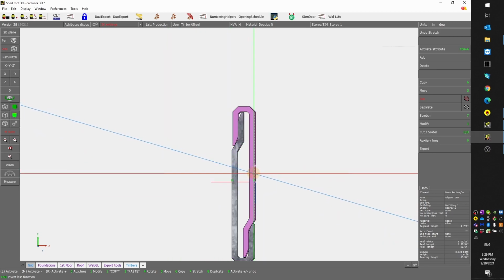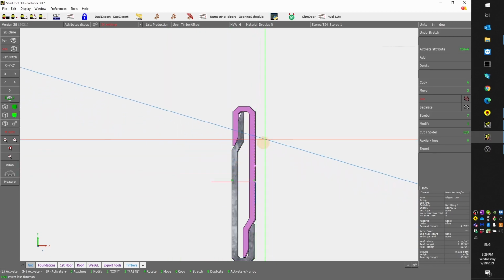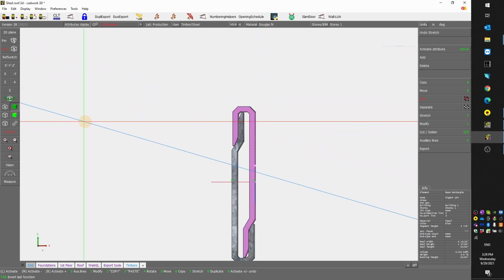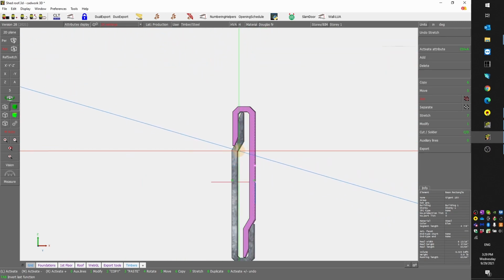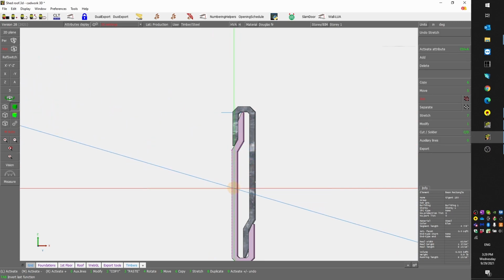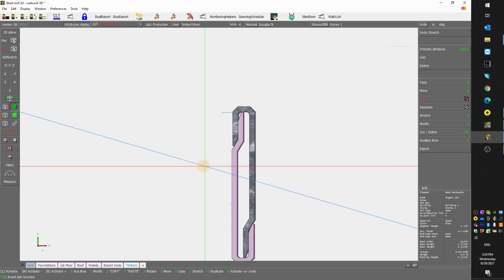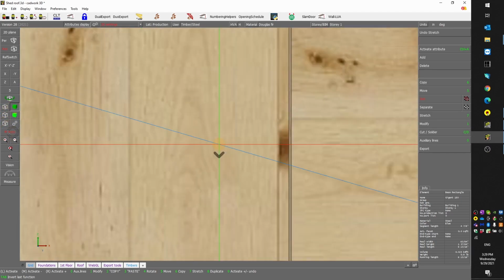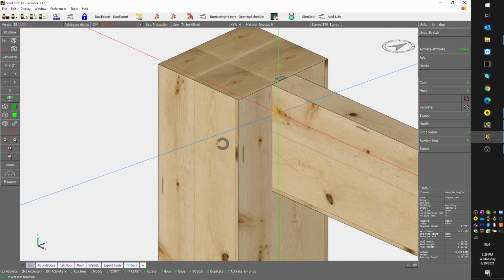This part will be attached to the girth, and it's going to drop and follow the dado until it is locked against or inside this part that will be attached to the column. So it all works. I can move forward to the next step.